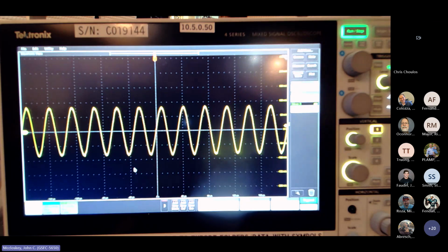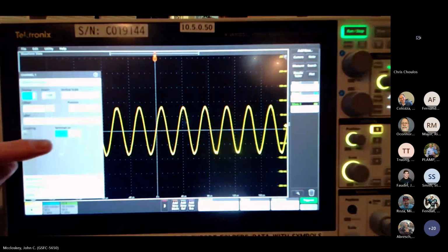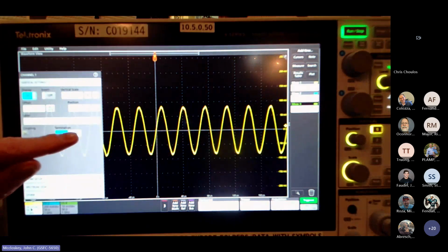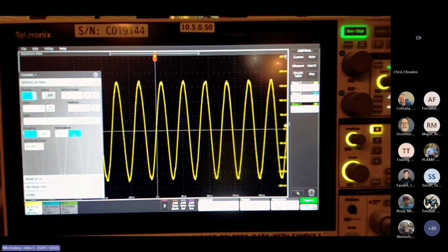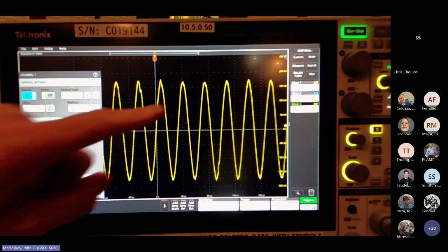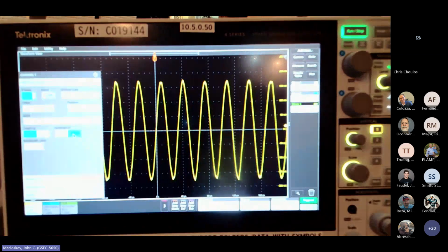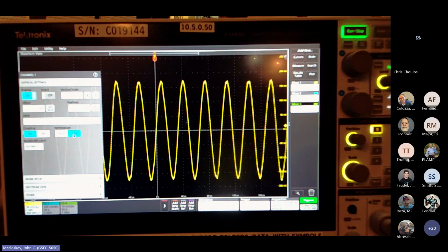And we were about 57.0 the other day on Monday, so in the same ballpark. And again, I'll go to a 1 megohm input. We're at 57 now. Go to 1 megohm. We're at about 119. So again, right around double. There's a little bit of noise there that's probably giving us a little bit of an exaggerated level, but for all intents and purposes, it's right around double. Okay.